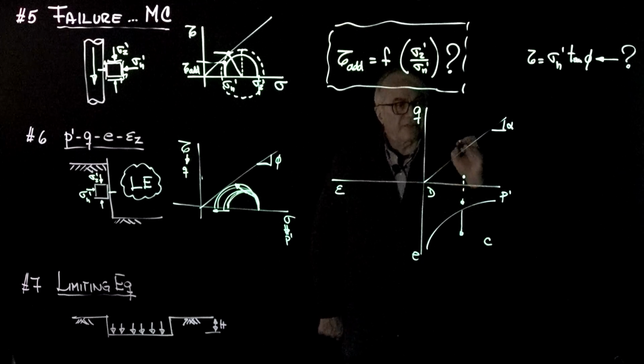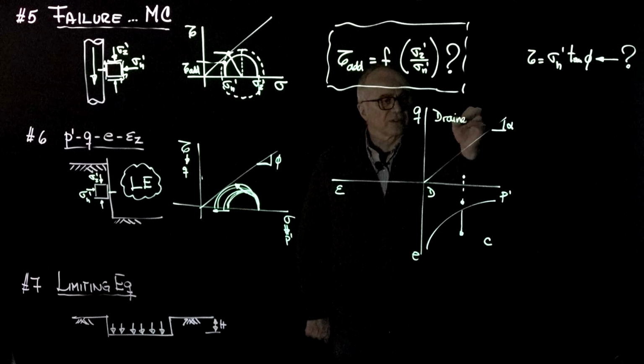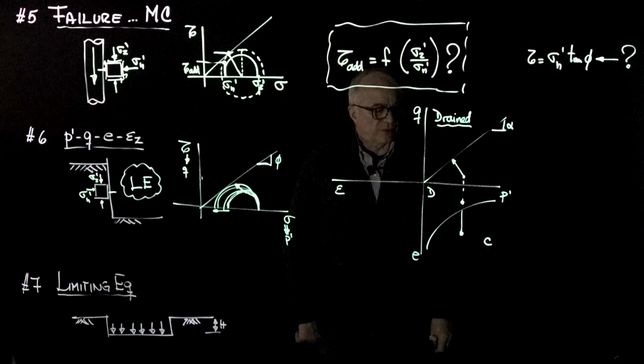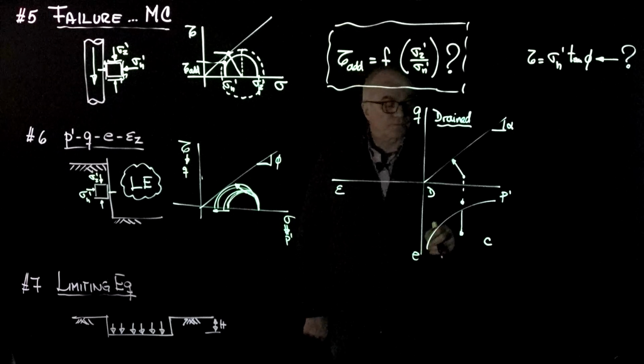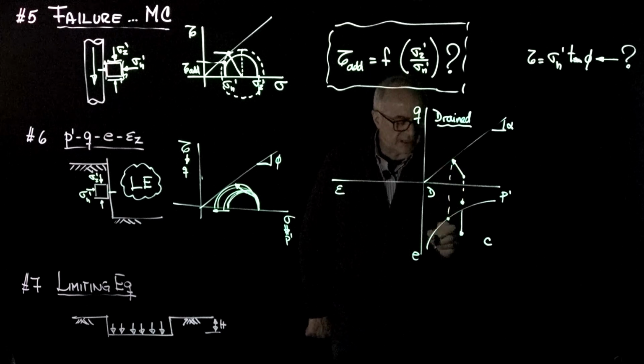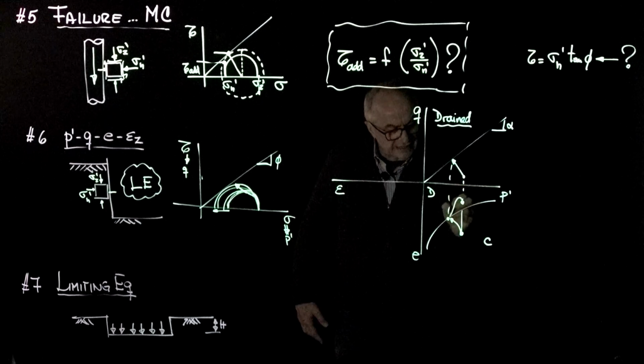But we know that in the case of drained situations, we know what the stress path will be. It will go at 45 degrees towards the failure line, and that is where it reaches failure. So this element will encounter failure, dilative or contractive will come here. The contractive will evolve in that direction. The dilative may itself experience some contraction and then it dilates.